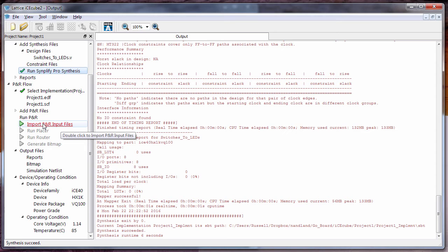Inside the FPGA there are about 1,000 of these lookup tables and registers and a bunch of components. You don't tell your code where to put the actual registers. That's the job of place and route: it takes the output of synthesis and decides where to actually map everything.